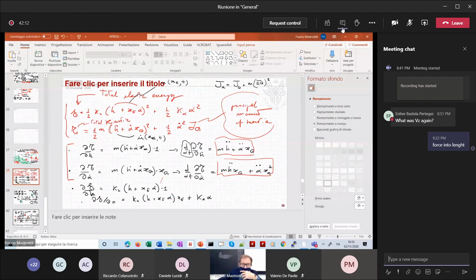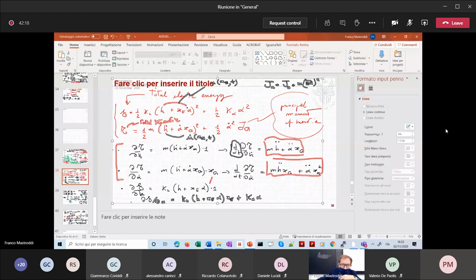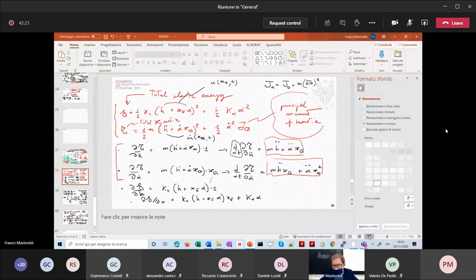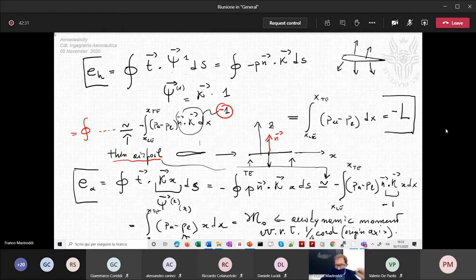that the Lagrange equations of motion are an actual means for describing the dynamic of the wing in a simple way. However, we discussed the generalized forces, the meaning of these two generalized forces. We have a moment for this, we have a lift for this, but this moment is now representing the moment of the aerodynamic load distribution with respect to 1/4 of chord.